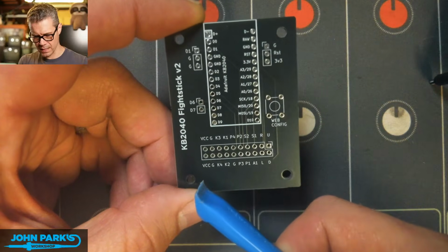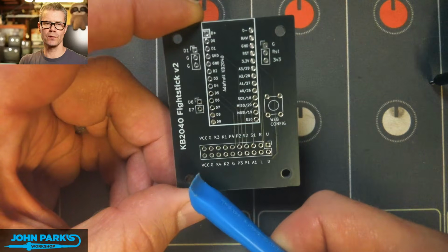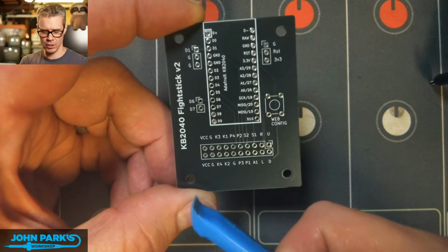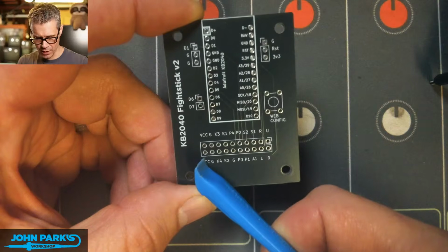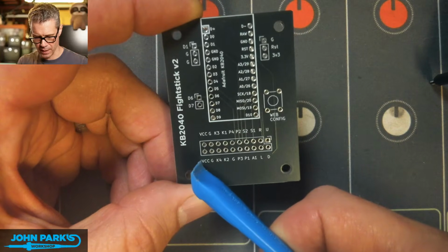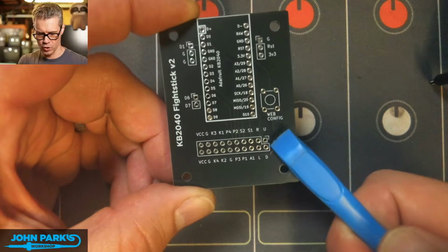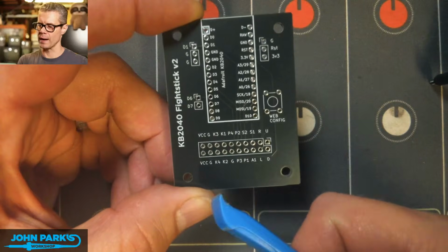One of the things that's nice about that, if you have those wires not even there, you can flip your harness cable upside down by accident because it's not a keyed connector, and you still won't fry anything. So if VCC were there, you'd be potentially frying something by sending 5 volts to the up and down joystick pins, as well as kind of messing with what's considered ground.